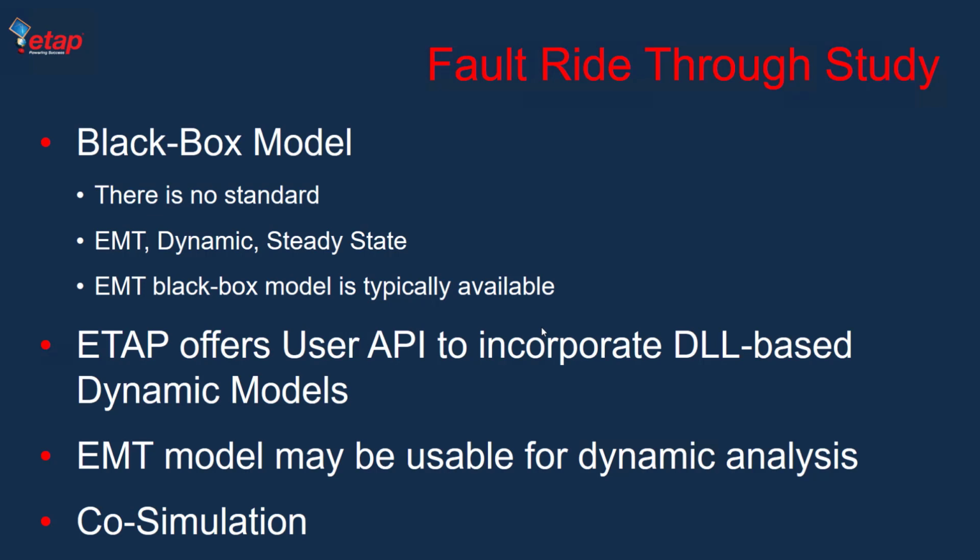Unfortunately, there is no standard yet on black box modeling, and the grid codes and standards are trying to mandate the vendors of the DERs to provide EMT, dynamic and steady state models. Typically the EMT model is available first, because vendors wrap the code that they use inside the controller, very similar or identical to a black box model, and then provide it to the clients.